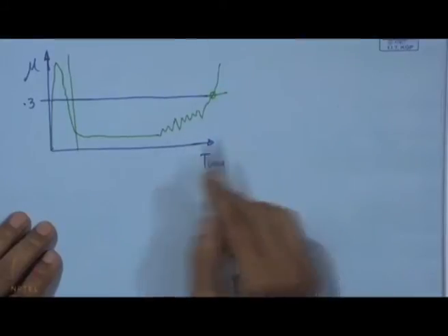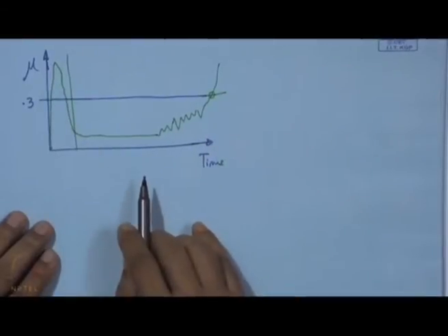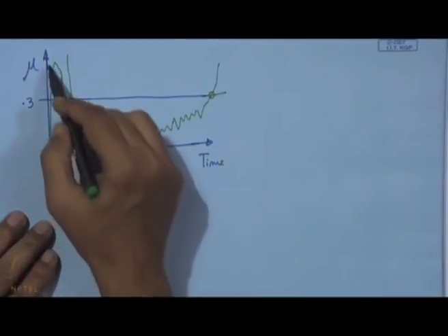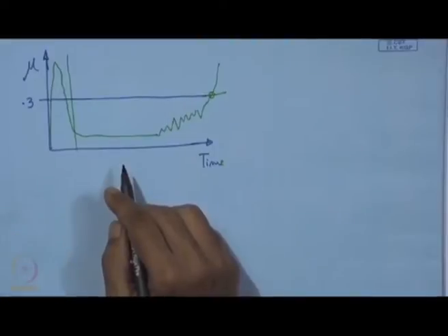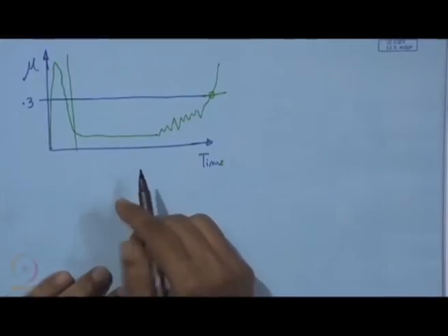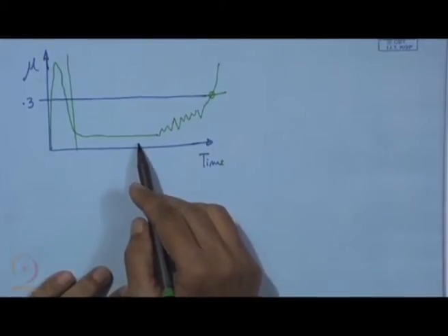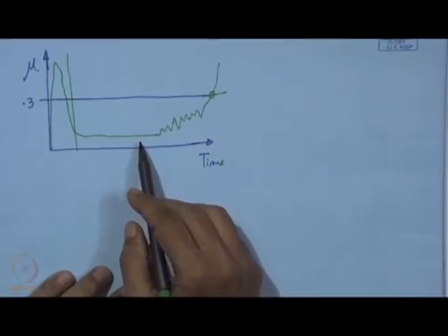But this map clearly shows how good or how poor the coating is and how long it can survive. So, looking at this graph, one has to find out a different graph for the same coating. It can be a PVD, physical vapor deposited, or CVD coating. It can be by the galvanic route.